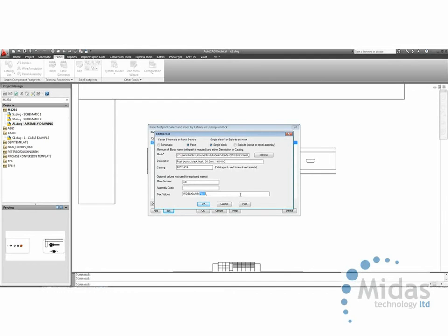Now you might not recognise what the PB11 is, but if this was a vertical switch it would be called VPB11, or if it was a horizontal it would be called HPB11. We don't have to put the V or the H in this value. So what this is going to automatically do, by defining in a catalogue list that the block name equals PB11 for this particular type of component, it will automatically find and provide us with at least VPB11 or HPB11 as the schematic symbol block.